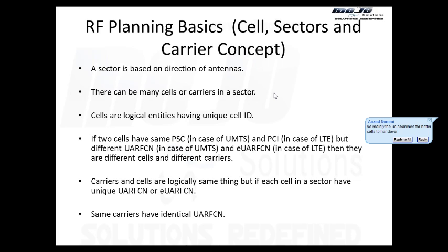Other frequencies can be other LTE carriers, or they can be another technology as well. So if you are on LTE, it can start measuring another LTE carrier, or it can start measuring UMTS, another technology. But for either to measure on another frequency, it has to go into compressed mode. Either it measures within the same technology, another carrier or another UARFCN, or within the other technology, it has to enter compressed mode.